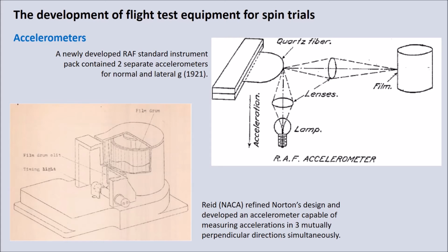Generally it was accepted that for your accelerometer to perform as best possible, it needs to be located as close as possible to the aircraft centre of gravity, and therefore also not shifting the aircraft centre of gravity around by putting some instrumentation that could potentially be heavy somewhere else on the aircraft.